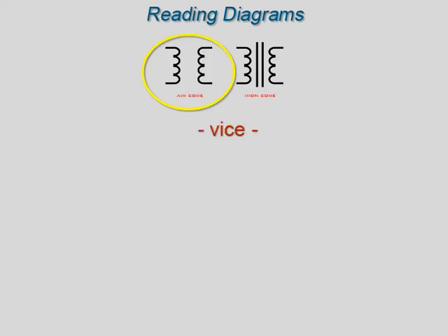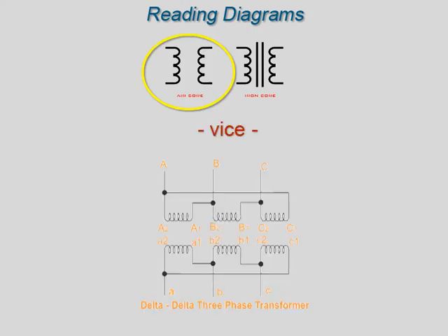In system single-line diagrams, transformers are often represented by the symbol for a single-phase air core transformer. However, that does not necessarily mean that the transformer has an air core or that it is a single phase. Single-line system diagrams are intended to convey only general functional information, similar to the type of information presented on a P&ID for a piping system.